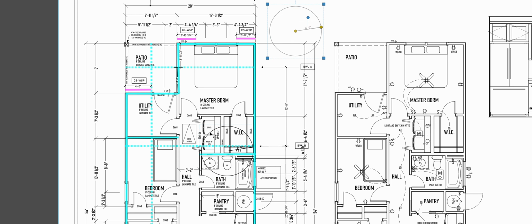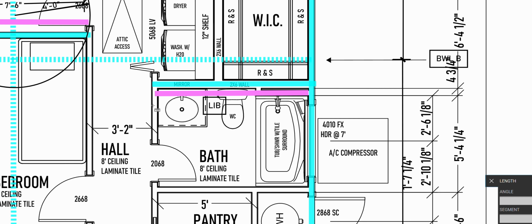And then how much length did I get out of it? Well, when this is framed, it's likely that wall is continuous and this wall is continuous, the long walls. So the short wall is going to be the one containing the lead and brace. So I'm going to be on the inside distance there. So inside a wall to inside a wall gets me 8 feet. Okay. So I got those. Let's move on down. So they're definitely not more than 20 feet apart in the middle. And I got a start and I got one on the end. Good to go.